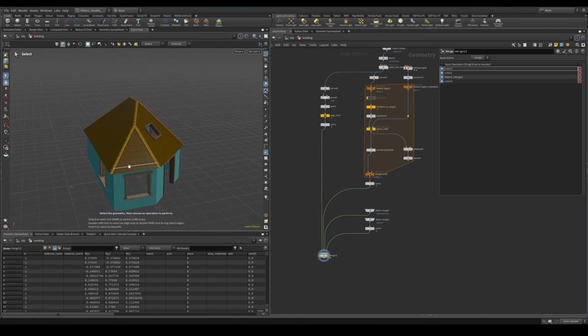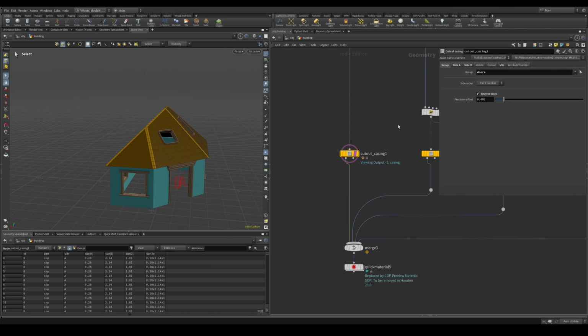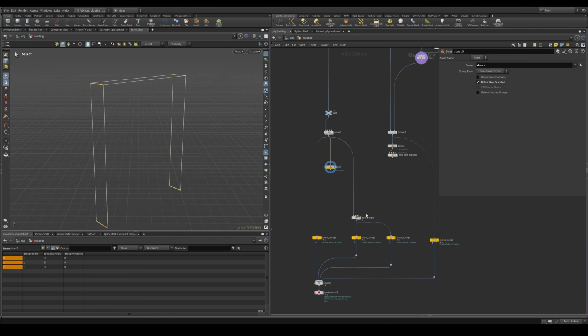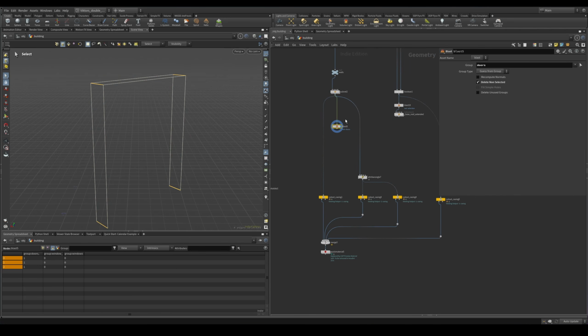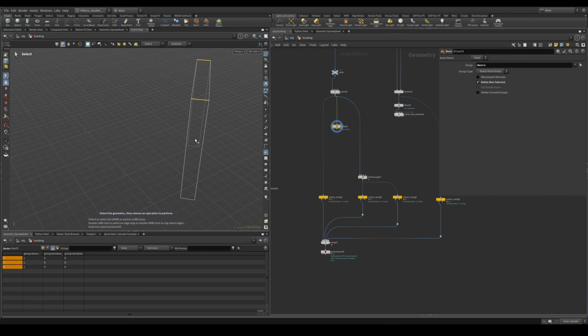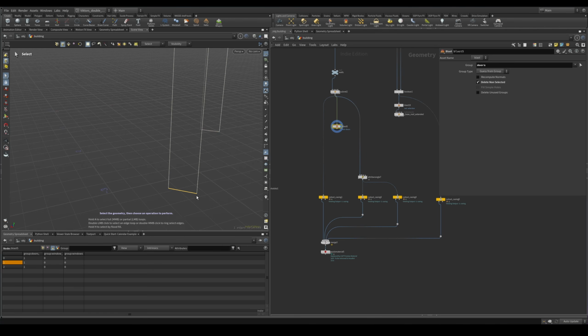And by default, you saw that I have not given any attribute values for it because by default, the HDA is set up to use the point number of the casing. So internally what this option does, it takes the input geometry, it figures out the internal edges of this geometry, and it uses the first one of these poly edges to create a direction of the casing.